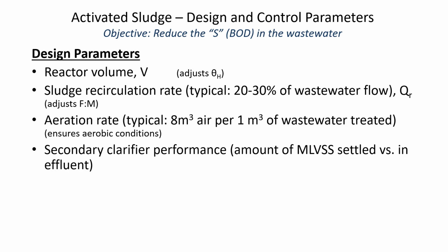The secondary clarifier, we care about how well it's able to settle mixed liquor volatile suspended solids. This abbreviation here, MLVSS, that means volatile suspended solids, is a surrogate for the bacterial load. So how many microorganisms? Suspended solids just means anything that's not dissolved. So it means solids that are suspended in the water. Volatile suspended solids is saying, well, let's exclude the inorganic component, meaning salts or anything else that's inorganic. So the volatile suspended solids is bacteria.